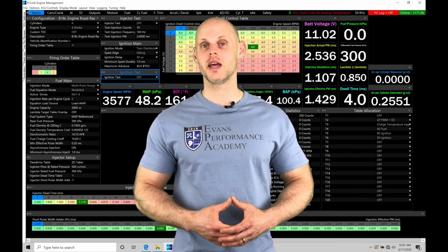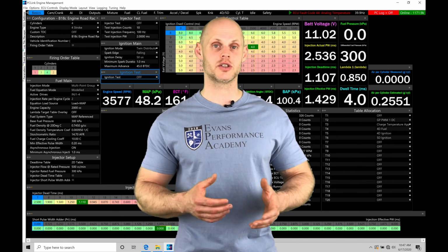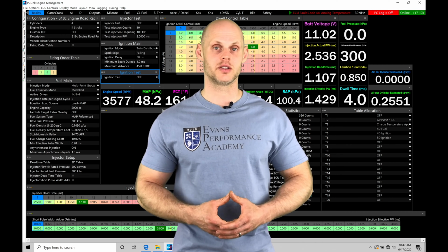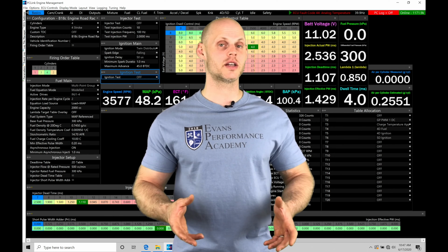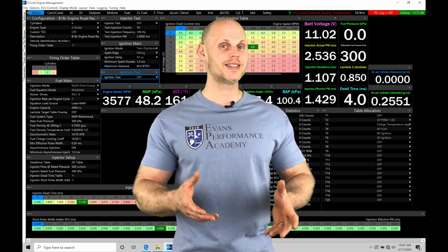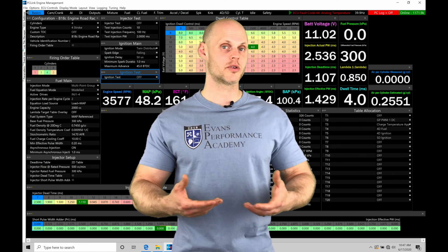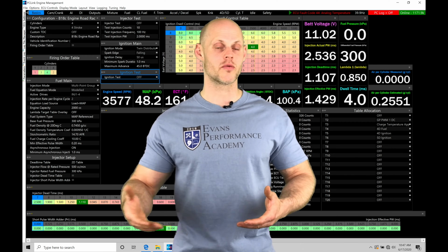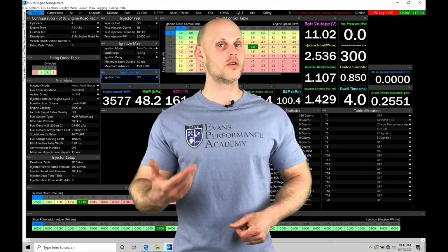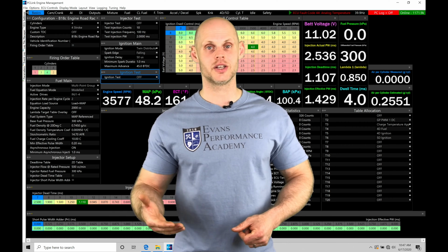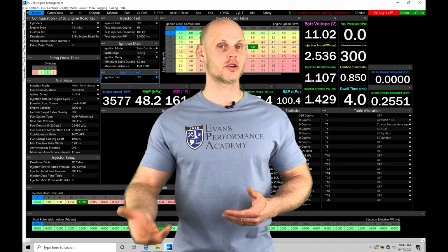In this video, we're going to be taking a look at working with our failsafe protection strategies we have in our PC Link software. So failsafe protection strategies are going to save our engine. We have our basic strategies such as our engine rev limiter and our overboost cut. So the limiter is not going to allow the engine to over rev past a certain RPM point, and the overboost cut is going to be cutting off our engine if we start to get too much boost generated on a turbo application.